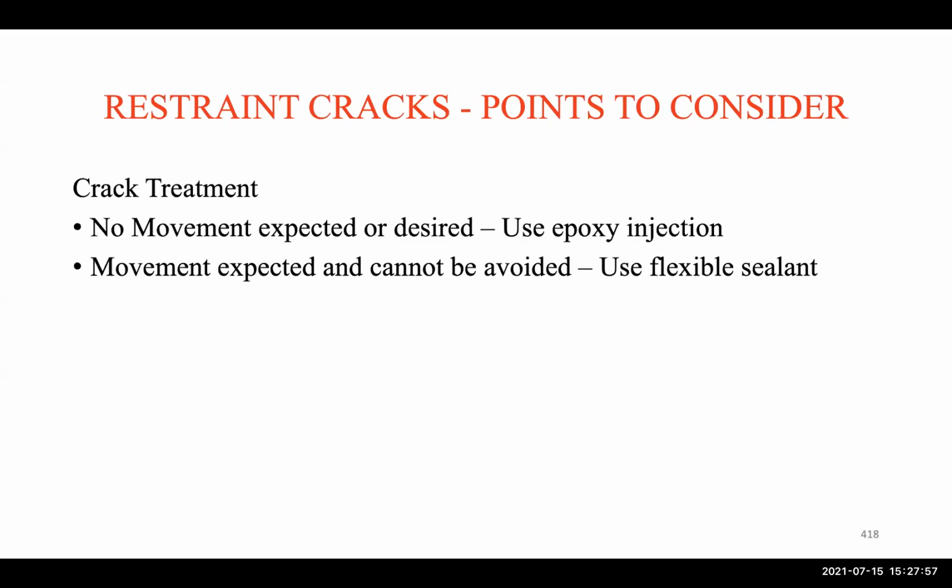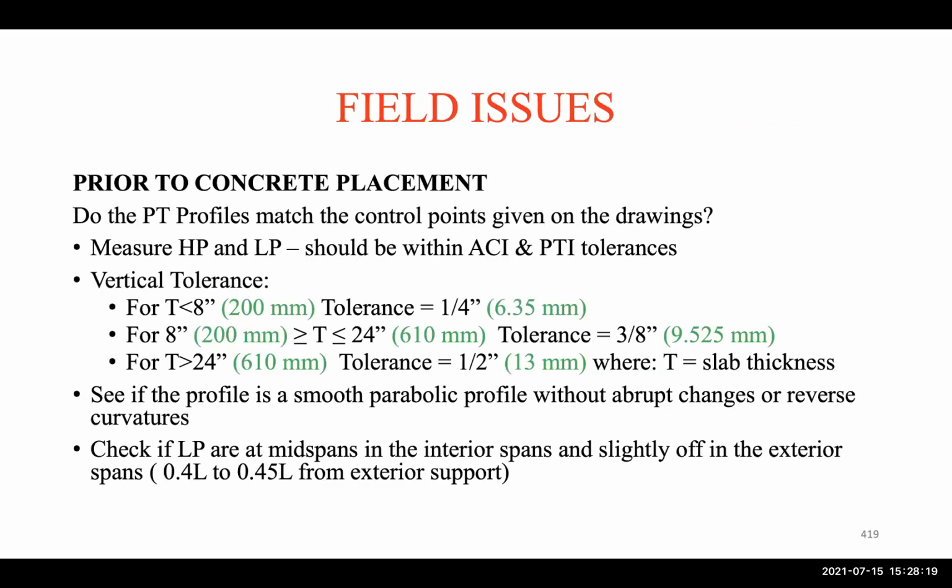Okay, crack treatment. So if we have cracks, how do we treat that? If the slab is not expected to move, then we use epoxy injection. If the slab is expected to move, then we use flexible sealant. So that's for causes of cracks, how we can deal with that in details, and then if we have cracks, how we can mitigate that.